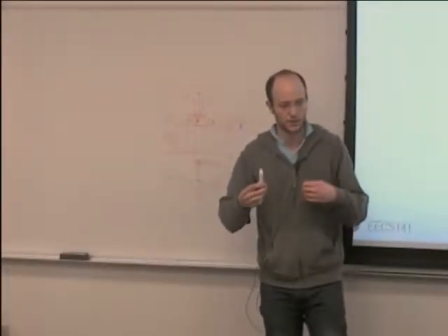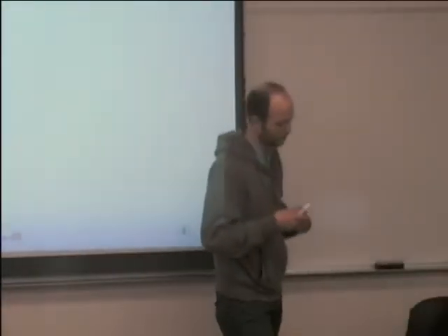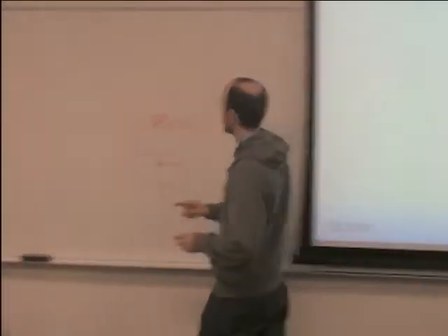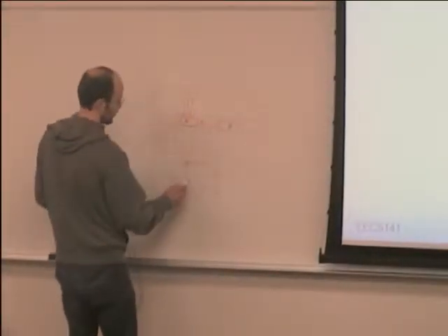So the analytical equations that you can use are of limited accuracy. Typically, the accuracy isn't sufficient for verification. It is sufficient only for design, okay? So when you go into verification mode, meaning you have a design and you think that it works and you want to make sure, then you will extract, and the tools typically do a much better job at calculating these capacitors for you.